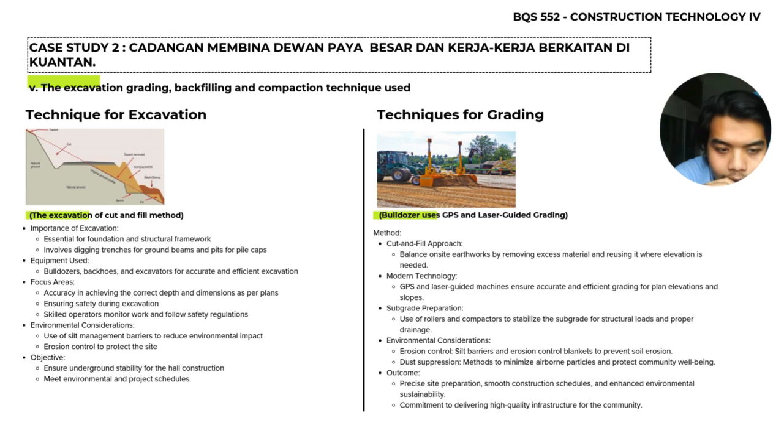And the focus area is to achieve accuracy in the correct depth and dimension as per plan, to ensure safety during excavation, with skilled operators monitoring work and following safety regulations. And for the environmental consideration, we use silt management barriers to reduce environmental impact and erosion control to protect the site.